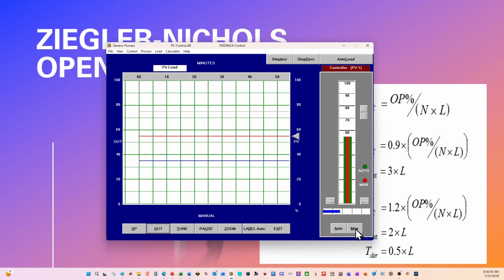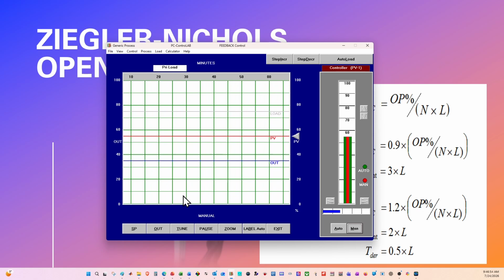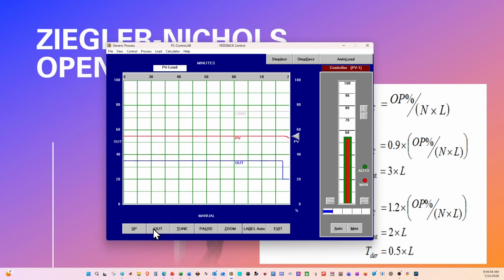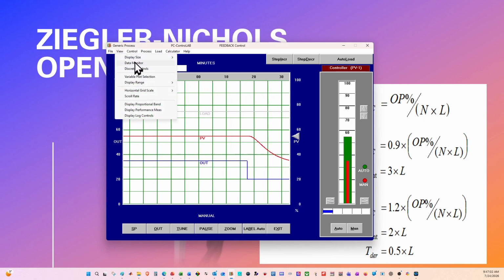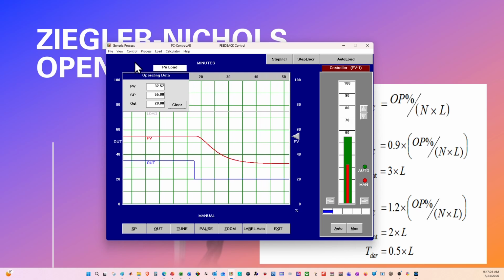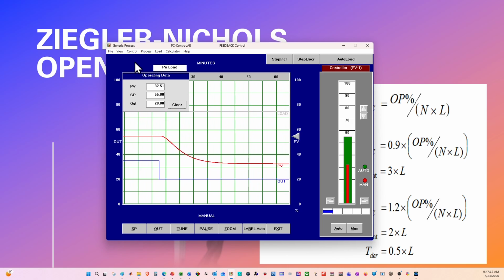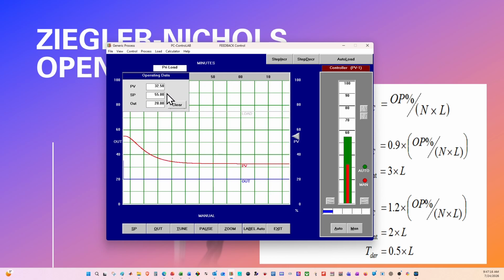Great, the controller will be put in manual, and the whole idea is that we give it a step change. So I'm going to take my output to 20% and allow the process to self-regulate. If we go to the data monitor, you can see that my output is sitting at 20 and my process variable is at 32.5. There is the output, there is the process variable.